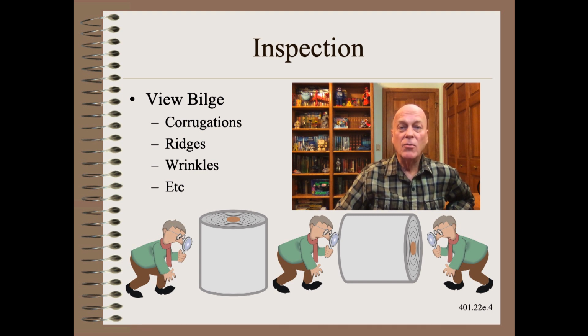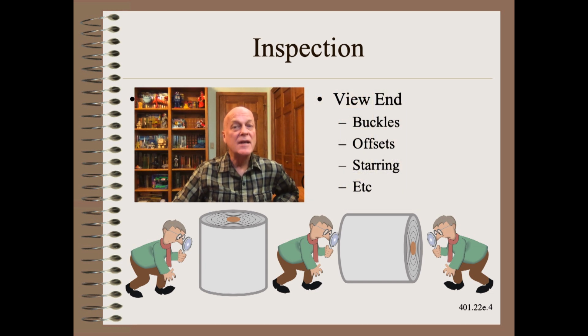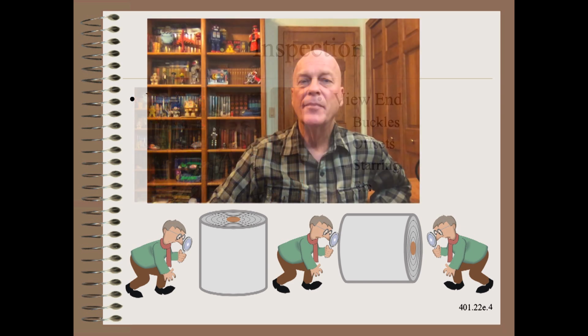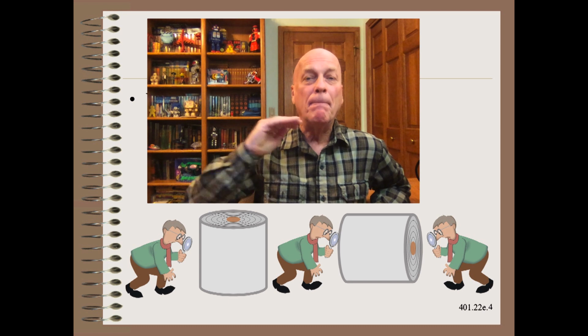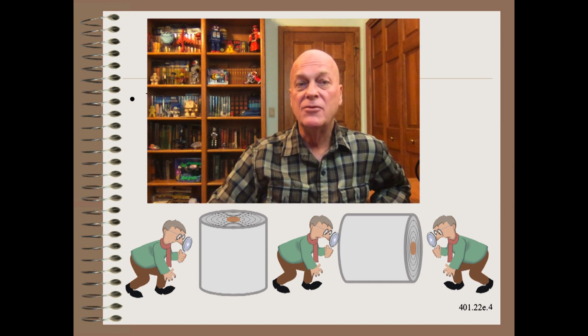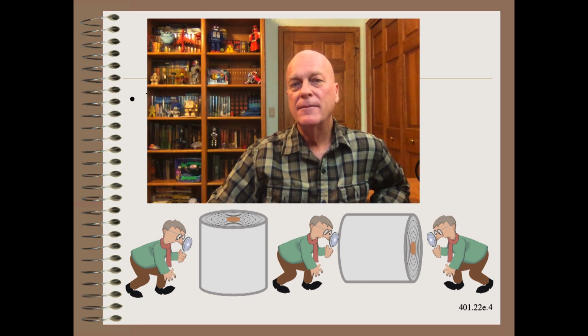Careful inspection of the roll's build gives several vital clues about certain roll defects that are often related to web profile variation. Careful inspection of the roll's ends gives us vital clues about certain other roll defects. Of course, our reference for troubleshooting is not whether the roll is rejectable. Rather, as we learned in an earlier clip, our references are deviation from perfect cylindricity, just as our reference for webs is perfect flatness.